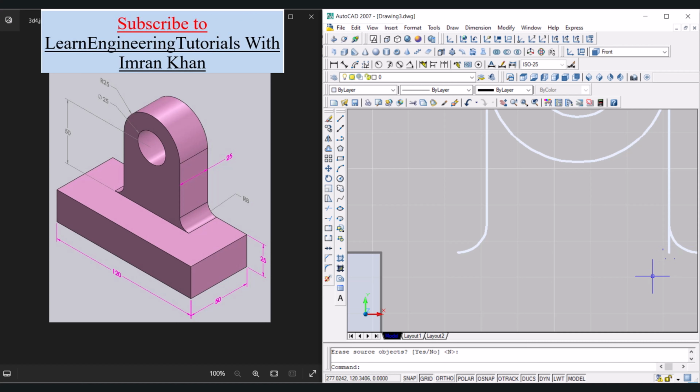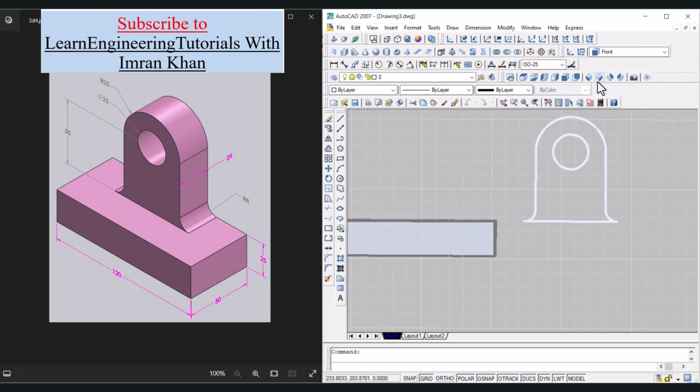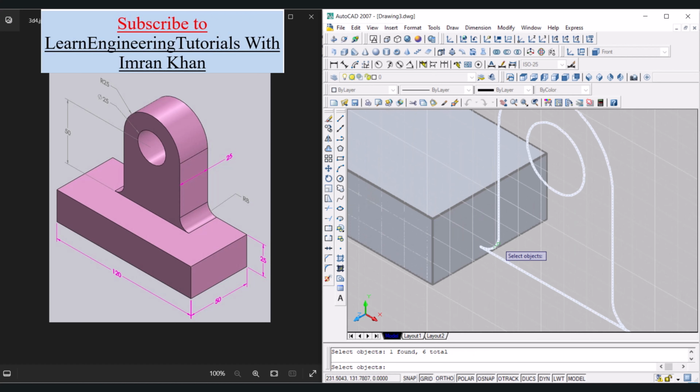Now use trim command, so TR, enter, enter, click on this portion and click on this portion of the circle as well. Now join the two arcs' endpoints, so click on line command, click on this endpoint, click on this endpoint as well, press escape. Visualize the object in the isometric view, so click on isometric view and now use region command, so click on this region icon, select these objects, this line and this arc as well. 7 found, press enter.